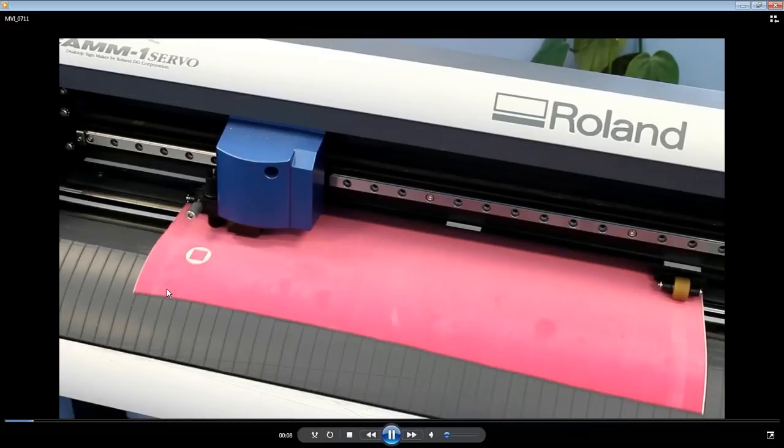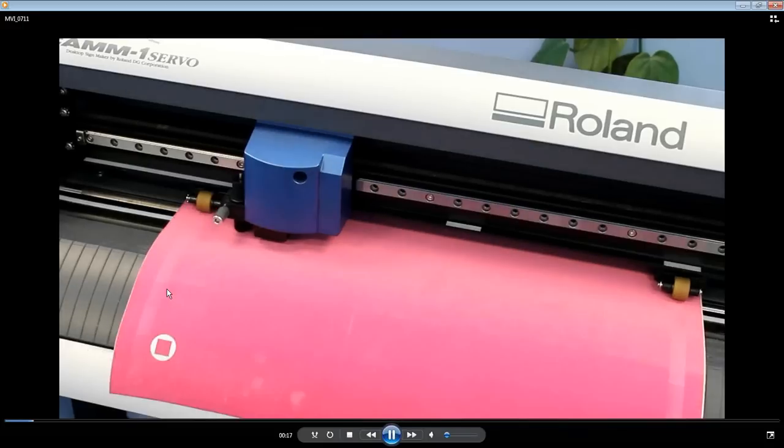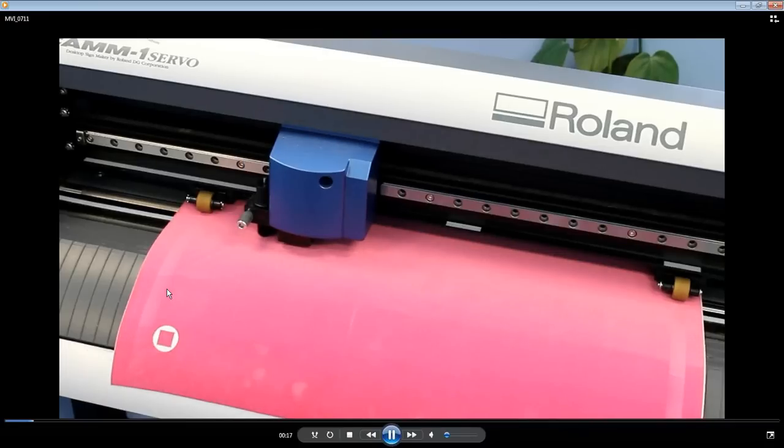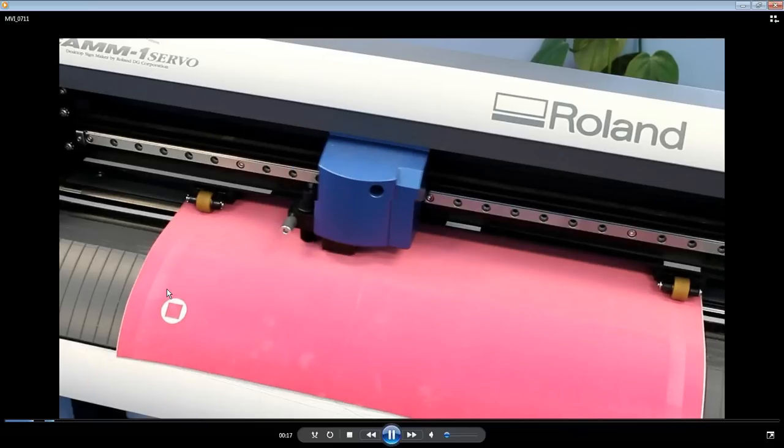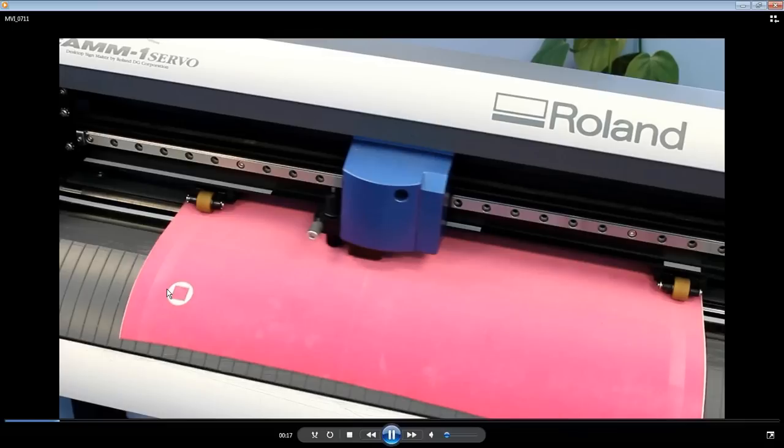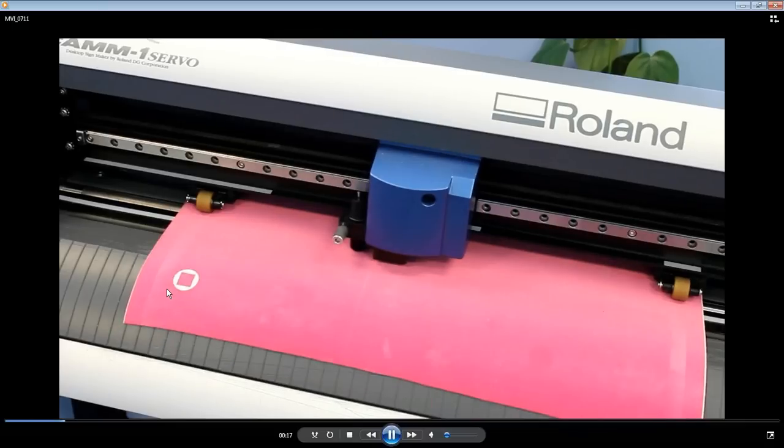Now you notice this is going pretty slow for this machine. This is only 10 centimeters per second on this GX24, and they're capable of 30 centimeters per second. And I've also changed the up speed on this. That configuration between slowing down the speed and slowing down the up speed on this is going to get us much better cuts, much cleaner cuts, much easier to work with design.